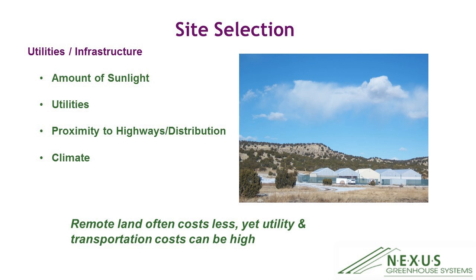Yeah, and then under utilities, I know there's also similar rules of thumb for electricity, and I know we've based on a 10,000 square foot module, we say that we need about a 300 kVA transformer for that size? That's correct. 300 kVA, because kVA works whether you're in single phase or three-phase 480. So ideally you would be in three-phase 277/480, but you could certainly get 300 kVA worth of power using single-phase power. It's just not ideal.